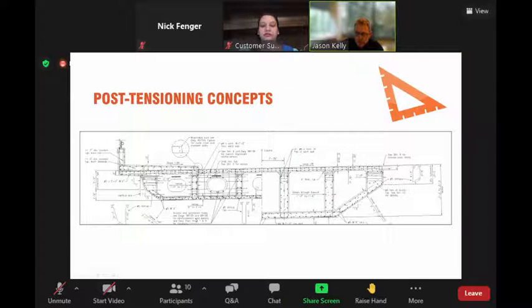It's not as deep. So if you're trying to get tall trucks underneath it, that's an advantage too. And that was one of the advantages here. Based on this bridge where we're widening it, it's actually sloping down. So the trucks were going to hit it. So we needed to come up with a better way to go thinner compared to the old section, or we wouldn't have enough clearance under it.